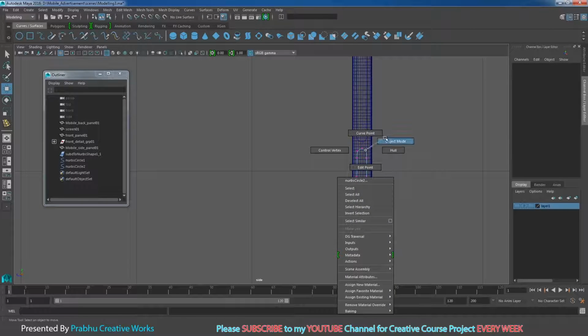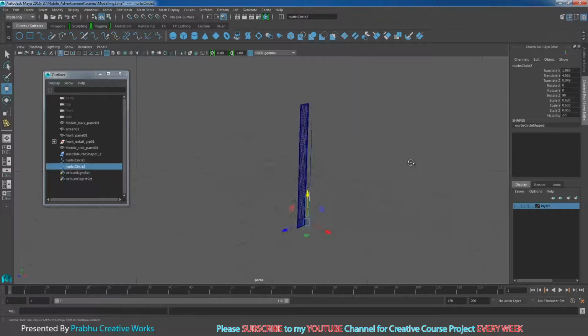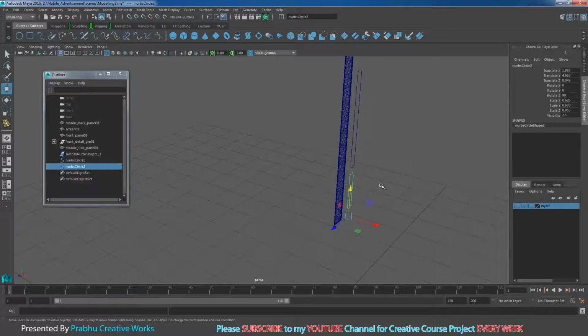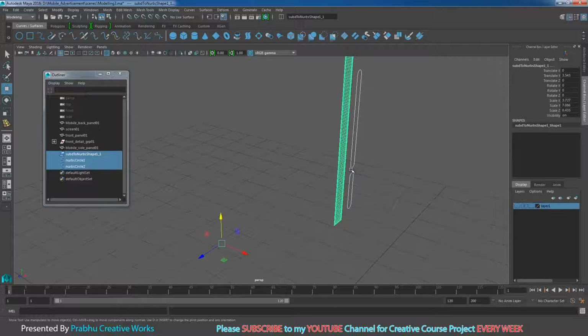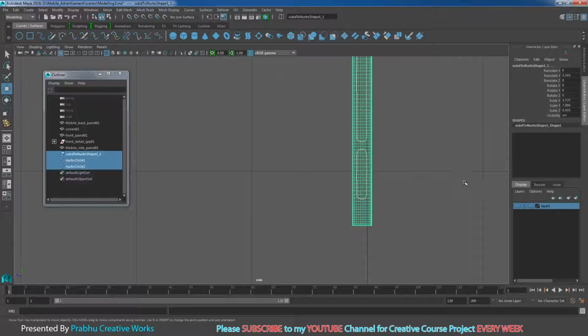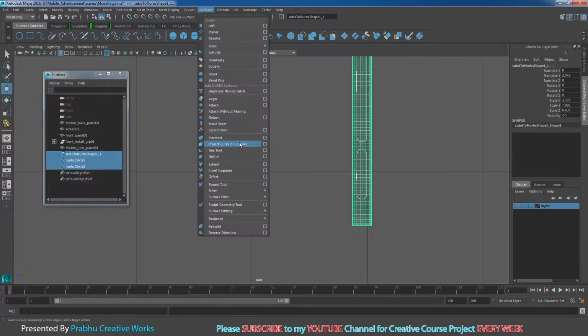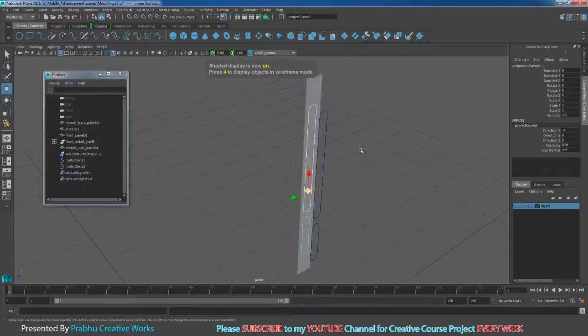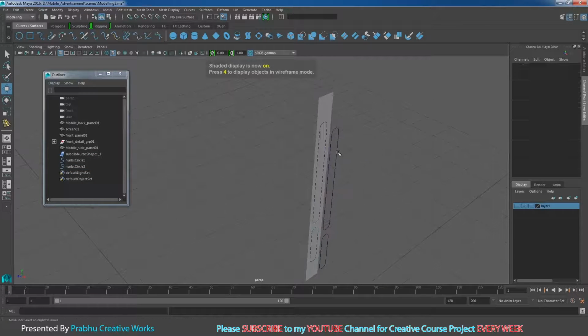So right click and choose object mode. So now we have to go over here. I will select this node circle and shift select this node circle and shift select this mesh. Go to right view and go to surfaces and choose project curves on surface. Now go to perspective, so press 5 on the keyboard. See here, our projection will happen.